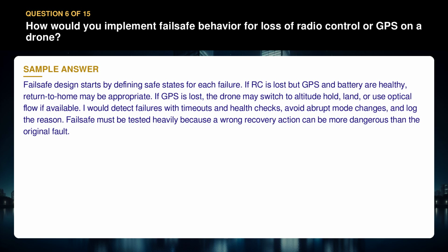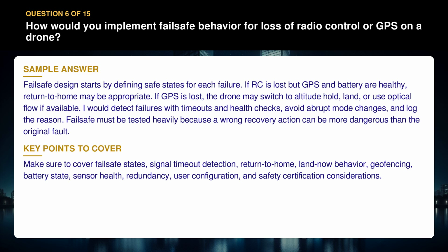I would detect failures with timeouts and health checks, avoid abrupt mode changes, and log the reason. Failsafe must be tested heavily because a wrong recovery action can be more dangerous than the original fault. Make sure to cover failsafe states, signal timeout detection, return to home, land now behavior, geofencing, battery state, sensor health, redundancy, user configuration, and safety certification considerations.